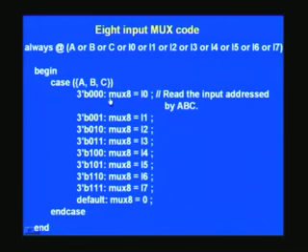And notice that we have only put one statement here. So occasionally you may have to put multiple statements, in which case don't fail to put a begin and end towards the end of that statement as such. And when we go for a demux implementation, which is the exact counterpart of this, then we can see more details on that.